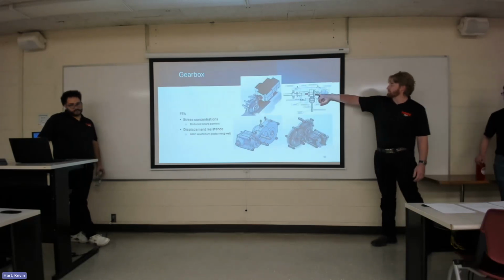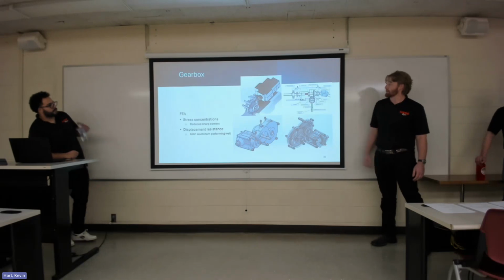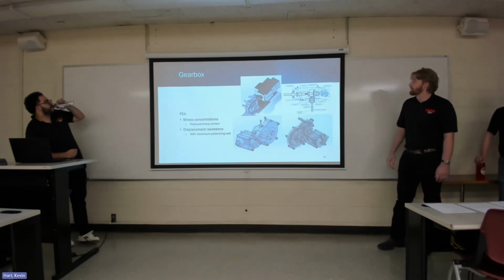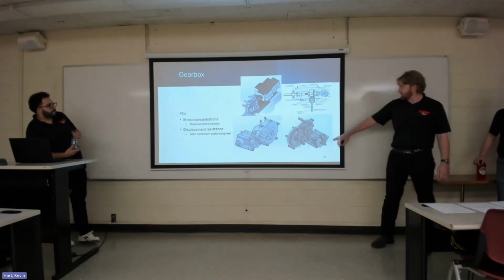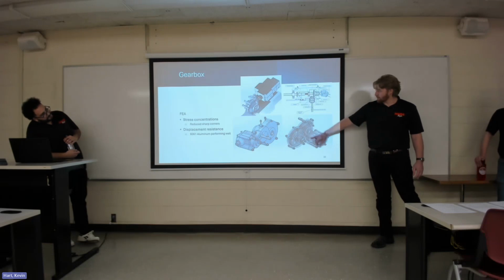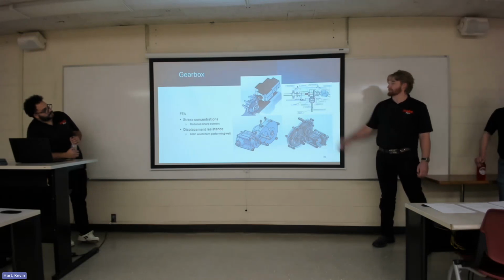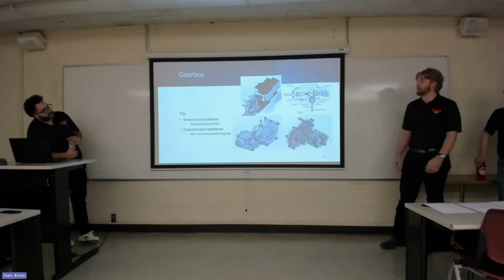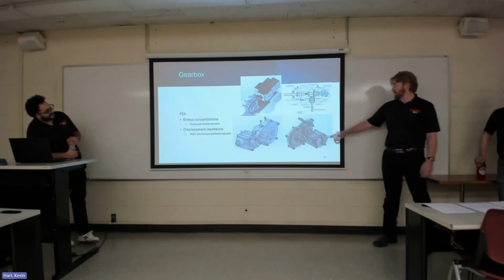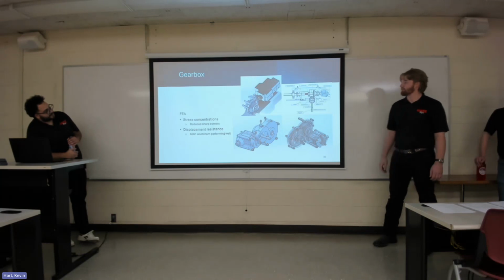So in this section view, you can see there's a lot of wasted space in this gearbox, and I made it really heavy. So instead of that, this you can see is a lot tighter pack. So it also allows for better lubrication throughout the competition. Because this one, we've just basically set a pool of oil in the bottom and just hope it got to all the gears. This one will actually have surface for it to flow around.